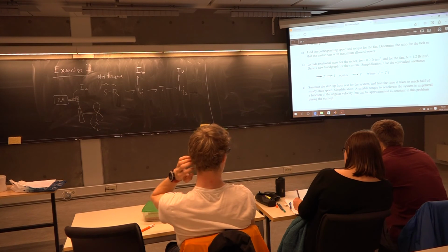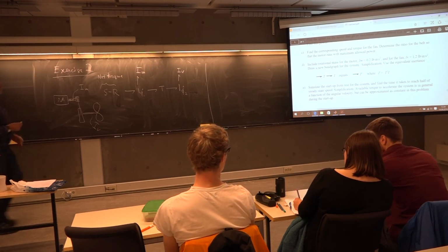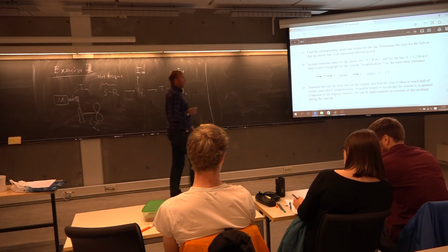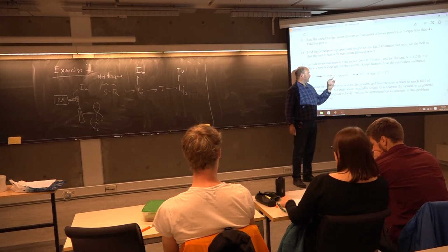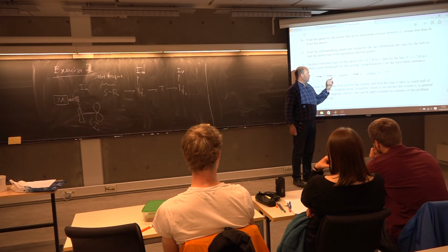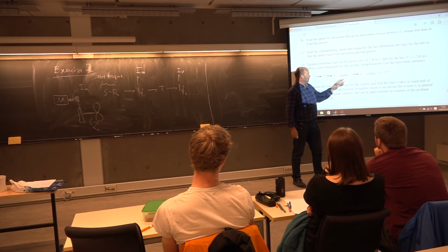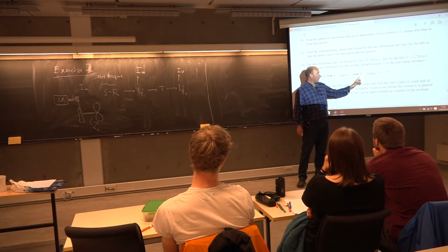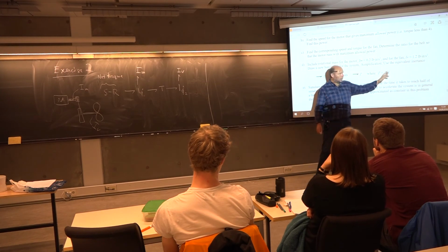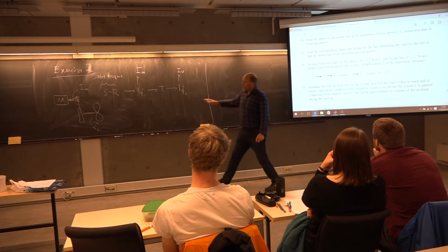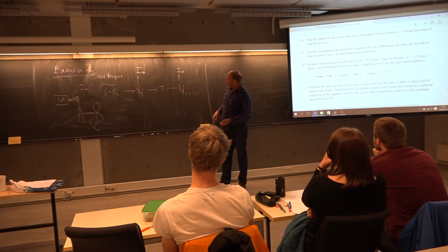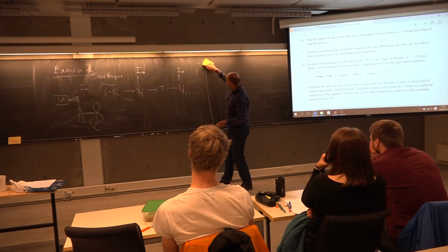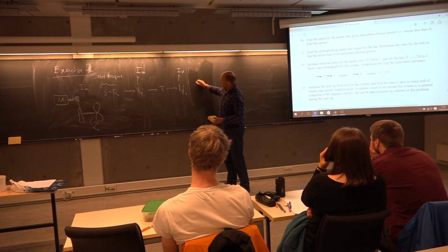When you have a transformer and then a mass, an inertance, hooked directly into it, you can simplify these two by an equivalent mass, where this equivalent mass equals the transformer value squared multiplied with Iv. So now you will have something looking like this.